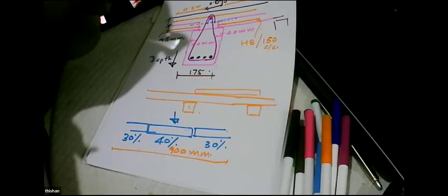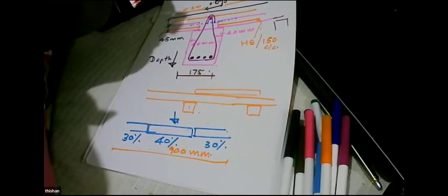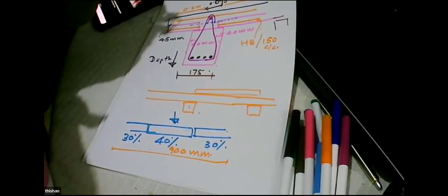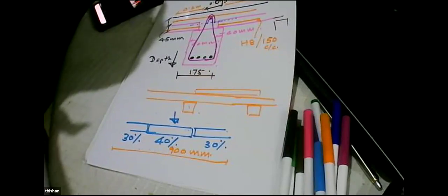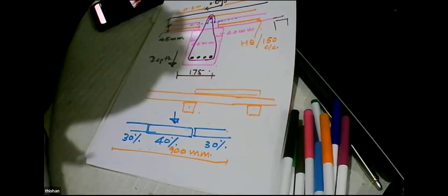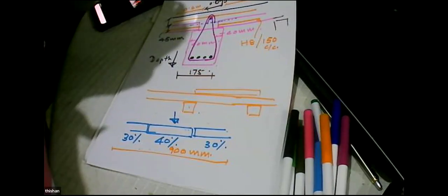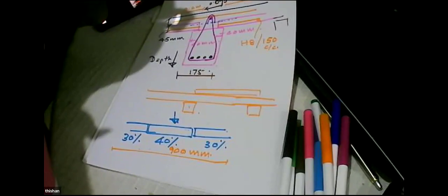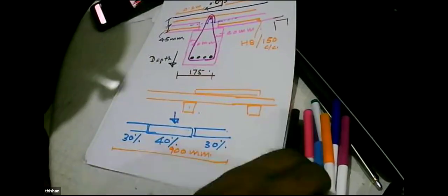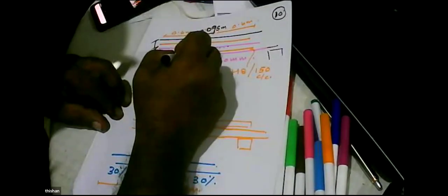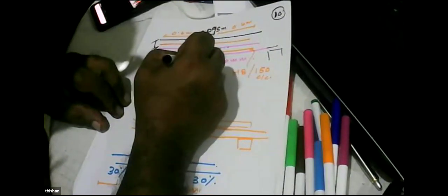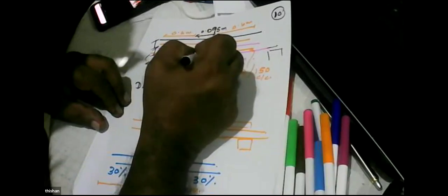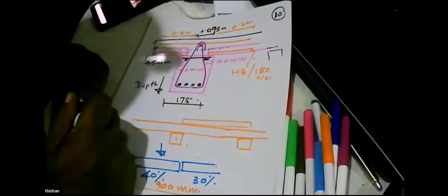There was a question at the very beginning. He sent one photo to the chat box, asking from the sketch we drew earlier about the bearing distance for the panels. The bearing, we have proven with testing. 40 millimeter bearing is the minimum, and anything more than that is more than sufficient. Do you remember, we have put two reinforcement here. That is to cater for it. We put a reinforcement here, and then this is a reinforcement. So because of that, there's no bearing issue.